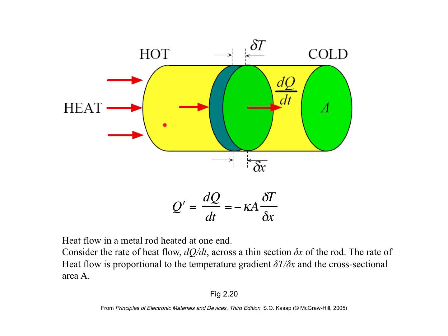The flow of heat from hot to cold can be considered like charge flowing through a conductor. The amount of heat that flows through a conductor should be proportional to the cross-sectional area as well as the temperature gradient pushing the heat through the material. Mathematically, the rate of heat flow, or the amount of heat being transported per unit time, is equal to the cross-sectional area times the temperature gradient, and a constant we call the thermal conductivity.